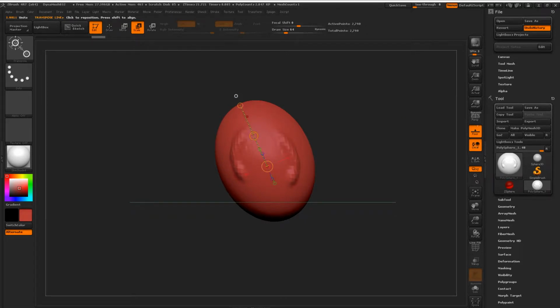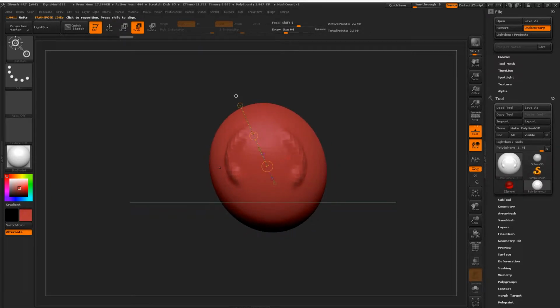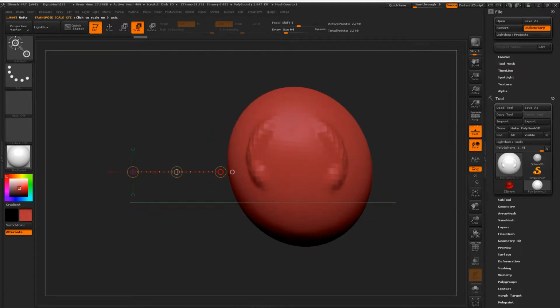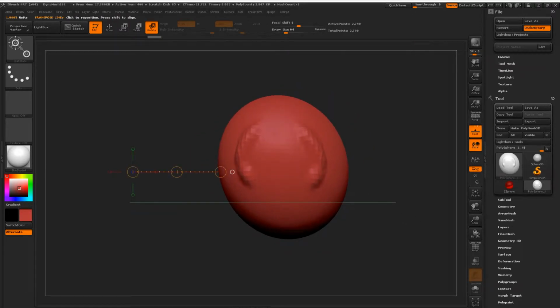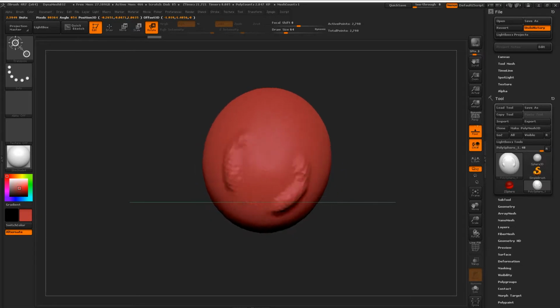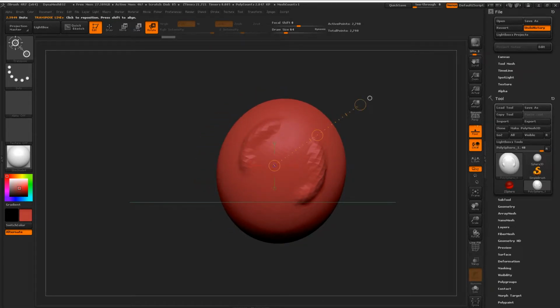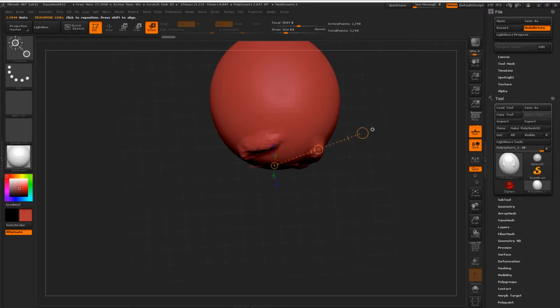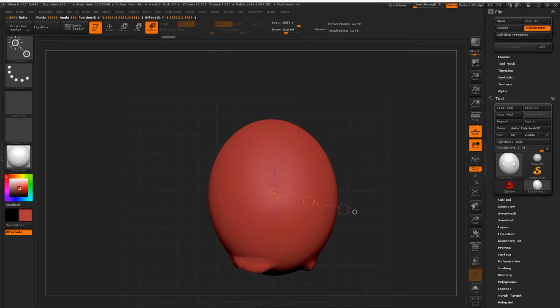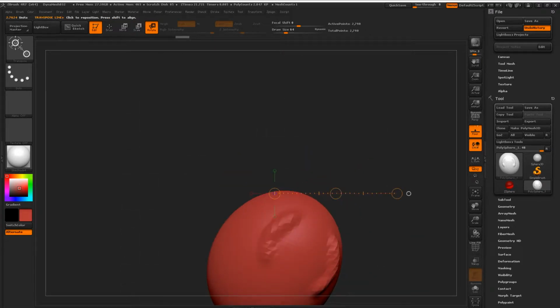Because if we grab this line and put it here, and now I scale, you'll see that everything's depending on where I place the transpose anchor points. From this point here, we can make a scale from this axis, as if it were an axis, okay? And with this key, obviously, from the middle point, we can make a line, and from here, we can spin the sphere. If we want to turn it from another side, we go to the top perspective, click, and with Shift, we mark so that the transpose line is stuck. And now from here, we can turn it, okay?